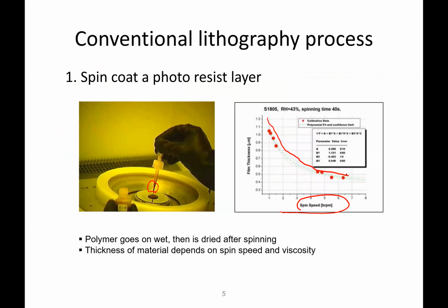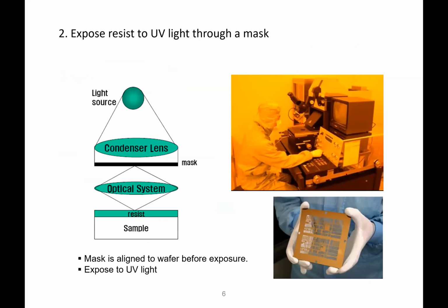And then, after photoresist spin coating, there is the soft bake. And then we can expose the UV through a mask. The glass has a certain pattern inside, normally made of chromium. Through the transparent glass pattern, the UV passes through, and then generates a chemical reaction on the photoresist.